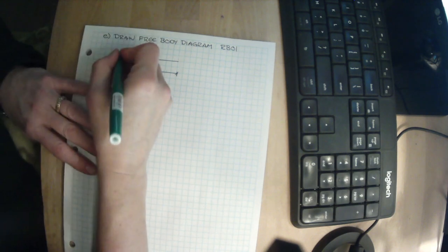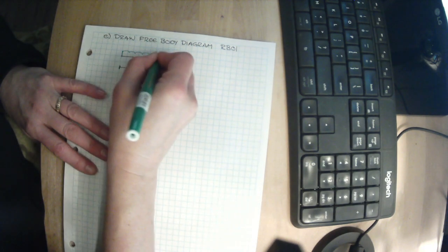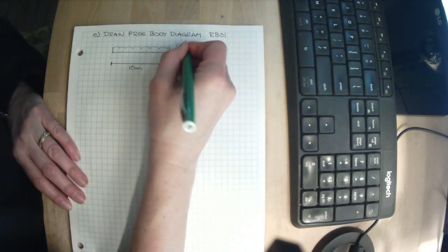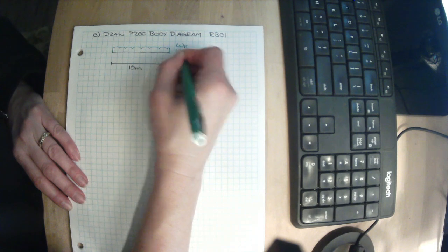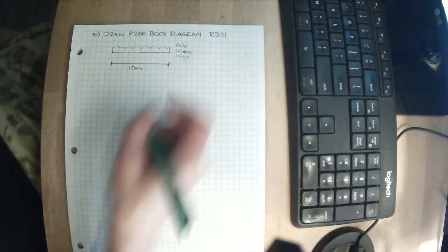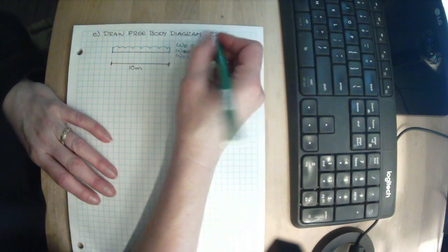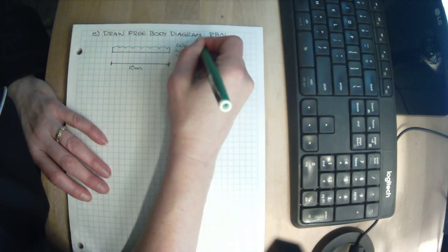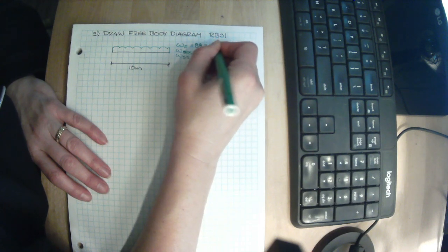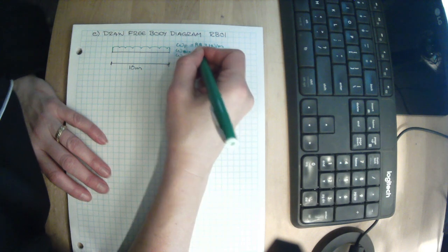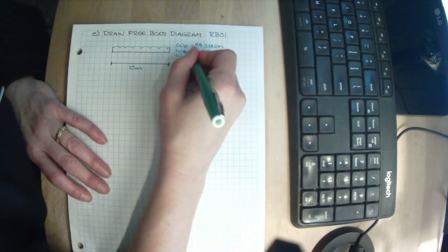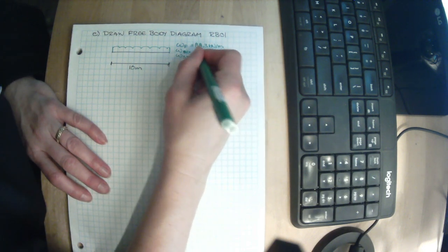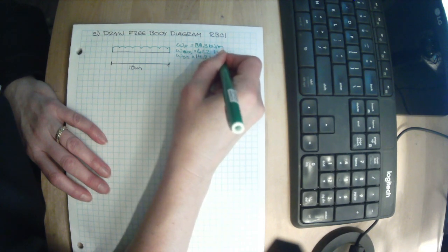We just calculated that it had a uniformly distributed load on it of either WF or W serviceability dead snow or W serviceability snow, depending on which condition we're talking about. And this was 88.3 kilonewtons per meter. This was 61.2 kilonewtons per meter. And this was 14.2 kilonewtons per meter.